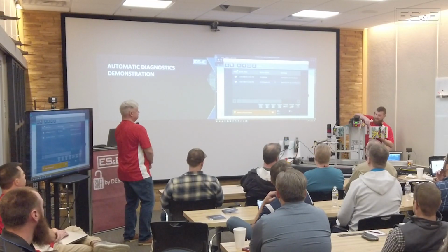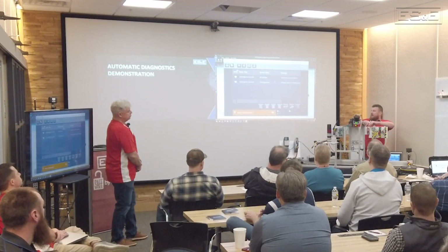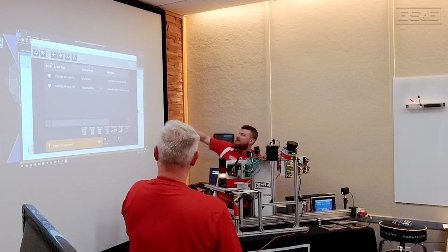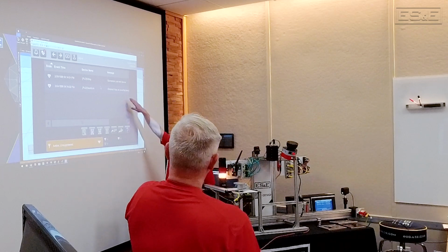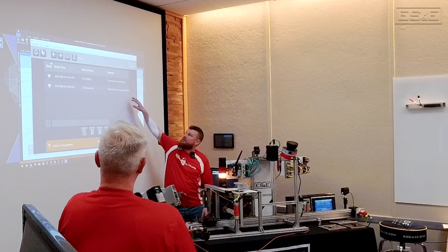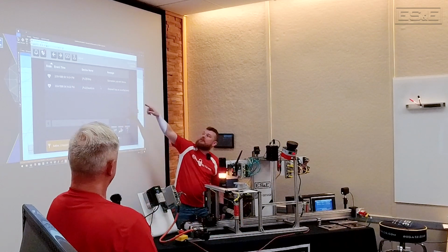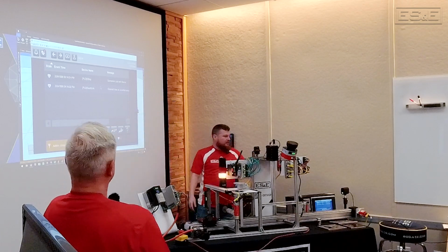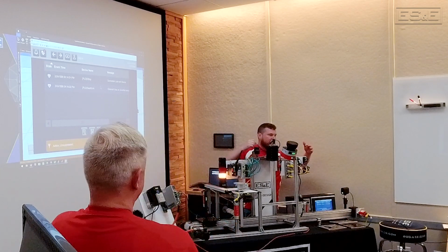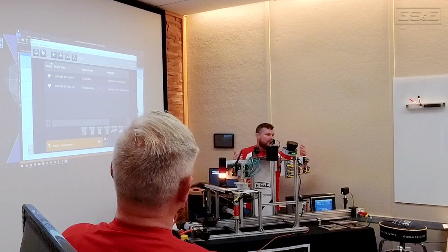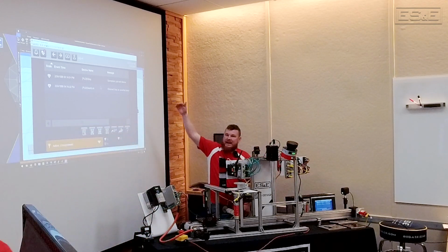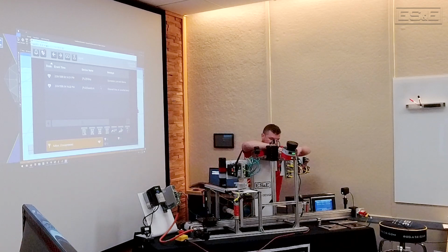So here what we've done, Hayden, we've disconnected our trunk line for our guard link, and you'll see here that channel 0 has an unverified device. So we've got the issue with the guard link, and it's also showing us that we've got a PLC e-stop. Because our safety circuit is not complete, it's going to prevent us from operating. So again, zero programming, it shows you exactly where to look, which is great.